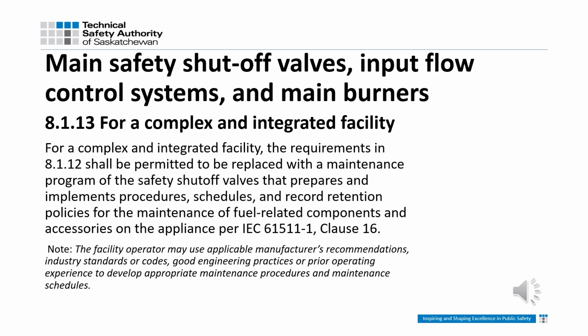8.1.1.3. For a complex or integrated facility, this allows you to replace the requirements in 8.1.1.2 with a maintenance program as per IEC 61511-1, Clause 16. Also see the note where the facility operator may use the applicable manufacturer's recommendations, industry standards or codes, good engineering practices, or prior operating experience to develop appropriate maintenance procedures and maintenance schedules.